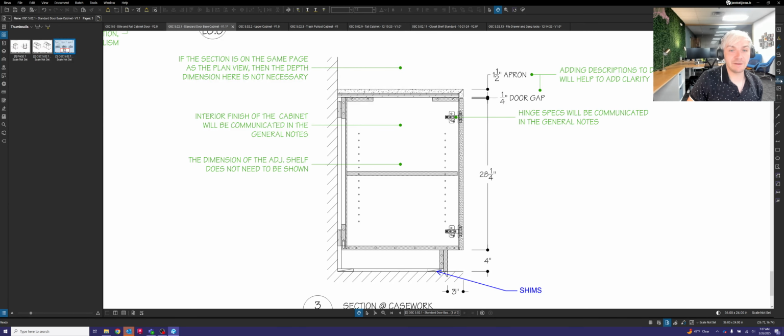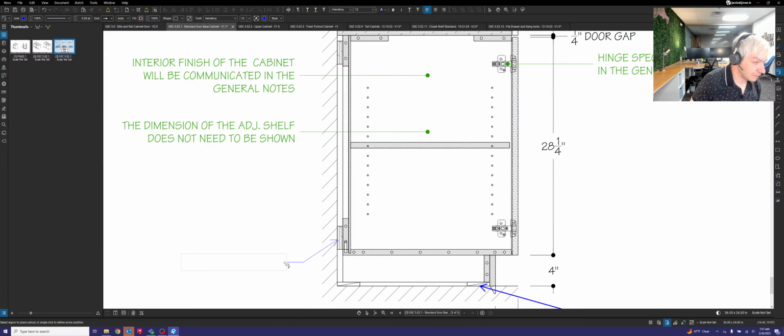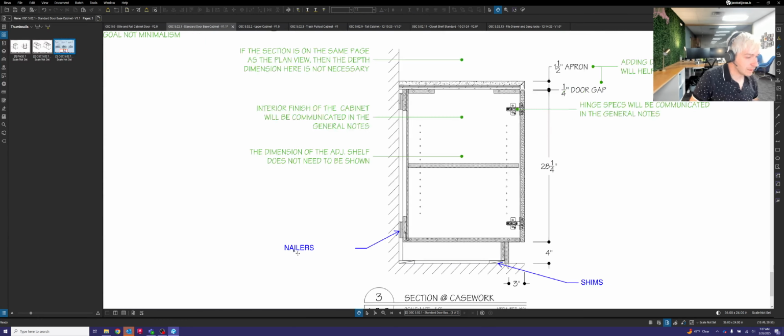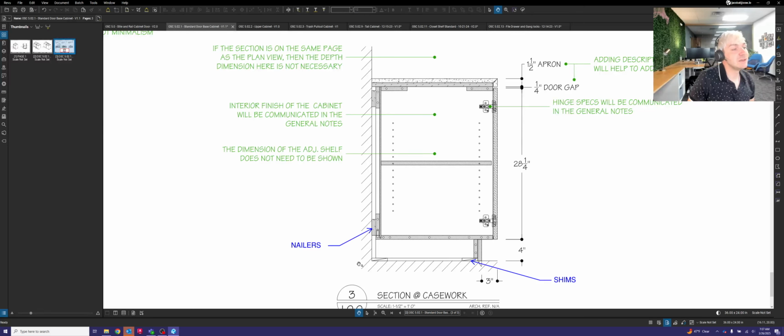At the back of your cabinet, you're going to see these wood blocks, just like this. These wood blocks that sit between the cabinet and the wall, these are called nailers. All right, nailers are typically going to be 3/4 of an inch thick by 4 inches tall, and they are usually used to be able to place... Well, we'll sometimes use shim here too, but nailers will be used to control how far forward the cabinet sits.